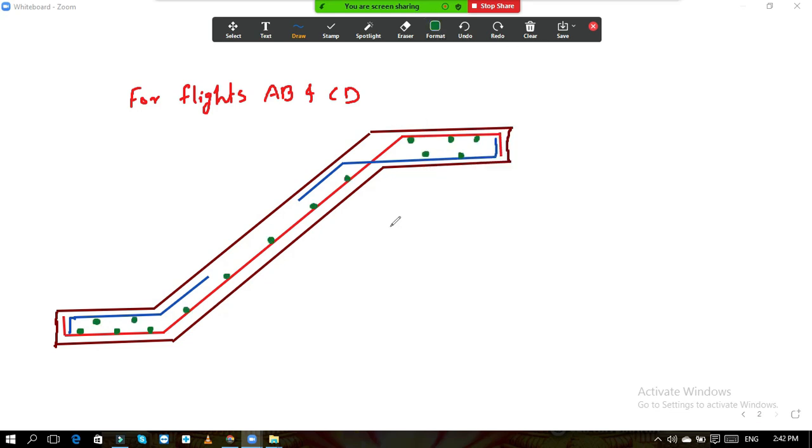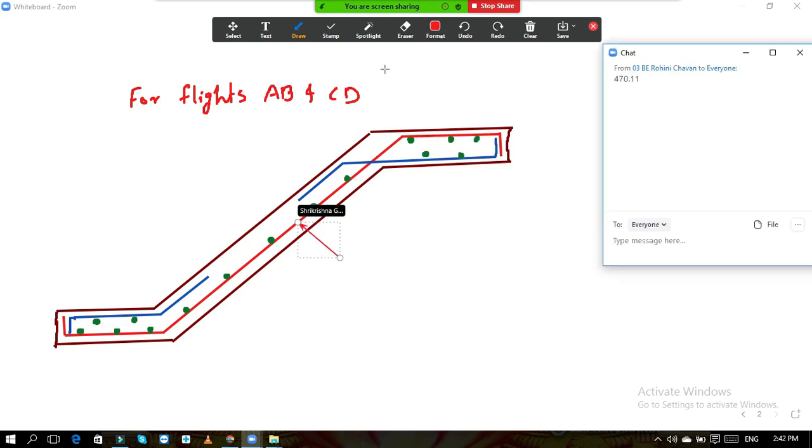Okay. Now we will give the names to these bars. The name of this bar is 10 mm bar about how much, it is main steel, so 100 mm center to center. If any spacing goes wrong, you tell me at that time only. Okay.